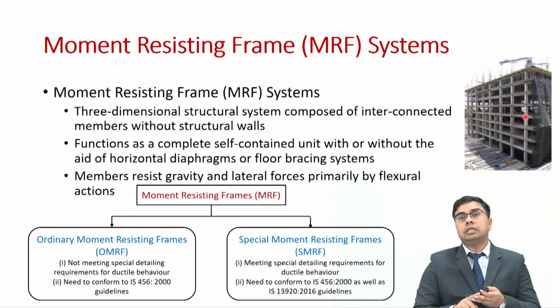After the plastic hinges form in the beams, if any failure is further to happen, then it has to be plastic hinge formation in the ground story column near the base of the structure, and only then can we allow plastic hinge formation in the upper story columns. Plastic hinge formation in the foundation is not at all expected.